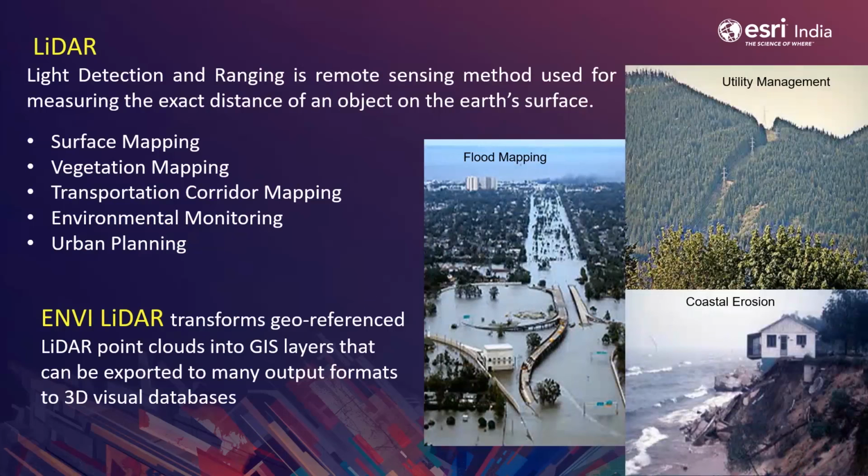As you can see, I have identified water, which has a low backscatter and can therefore be seen at the bottom of the plot, while built-up area shows a maximum backscatter and is therefore at the top of the plot area. While crops show a very significant, continuous and similar pattern and can be classified.